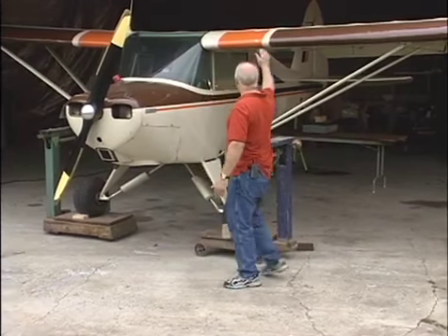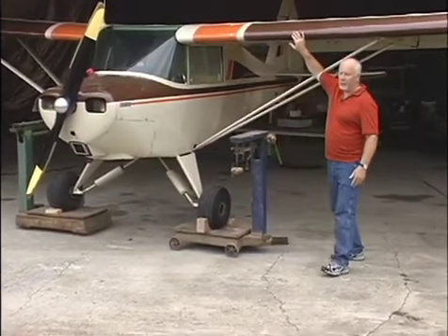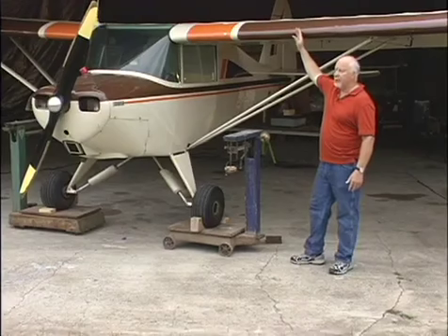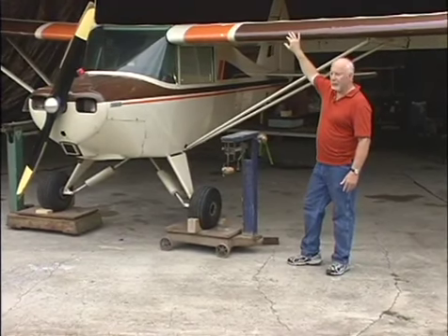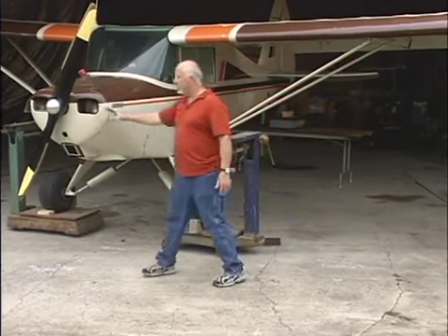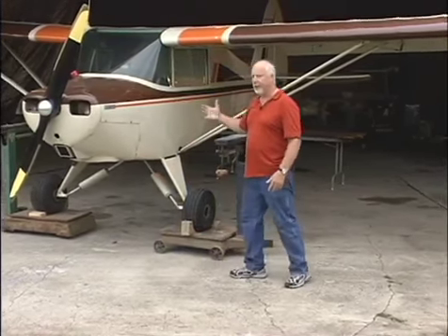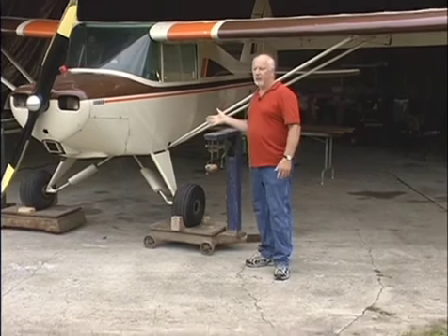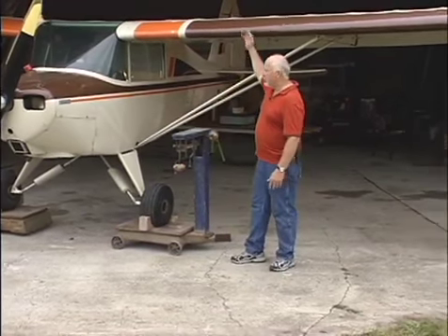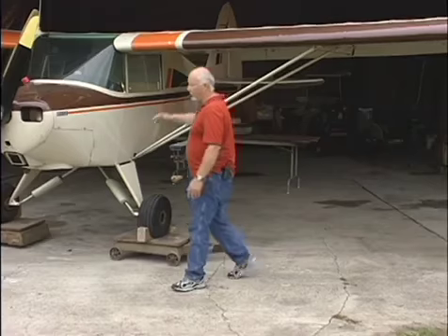And some people pick the leading edge of the wing. But you want to pick an area that is not going to change. For instance, if you picked something on the engine mounts, they will wear after a while, and so they could change. Same with the landing gear. So it's quite common to use the wing leading edge or the firewall.